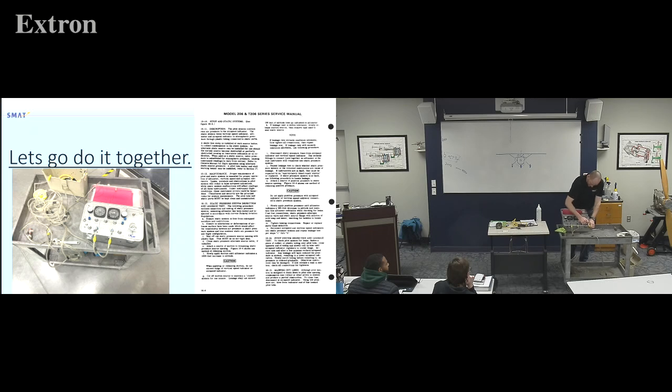Let's try that again. Give myself some vacuum to work with. Alright, so I'm at 900-ish. I'm going to raise it up till I'm 1,000 above 900. Notice this side's moving. It's because I don't have the cross feed open, right? So I lowered the pressure on my pitot system, but my static system is just reading atmospheric yet. So if I have both of them plugged, oh, that's tough stuff. If I have both of them plugged, ooh, sheesh.